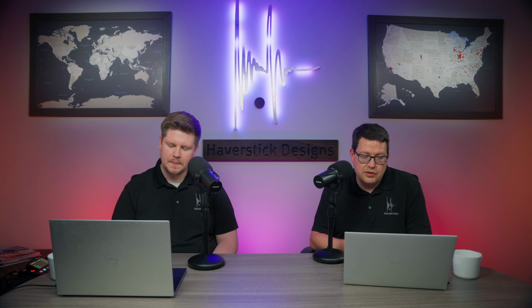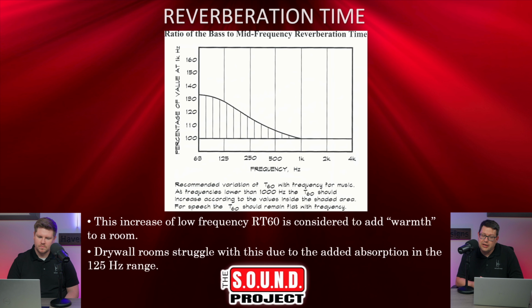But this chart that we have here on the screen is what's called the bass ratio. For rooms that are for musical applications, especially concert halls, you want the low frequency reverb time to slope up a little bit and be a little bit longer in the low frequencies than it would be in the mids and the highs, because that gives a bit of a musicality and a warmth to the sound. This is all subjective, but it's based on studies that have been done over the years.